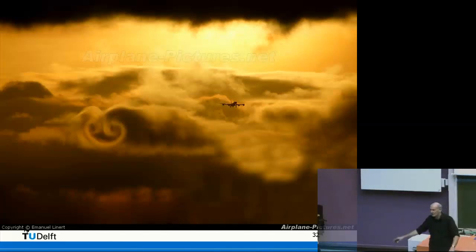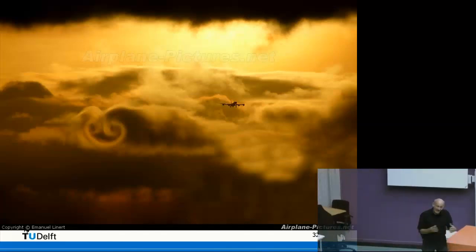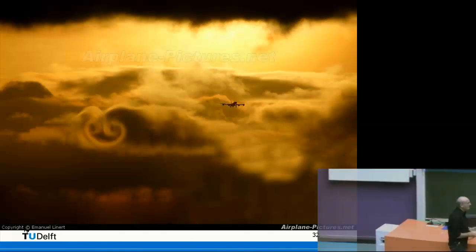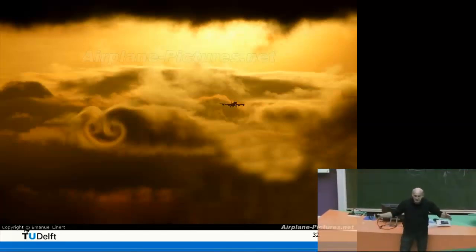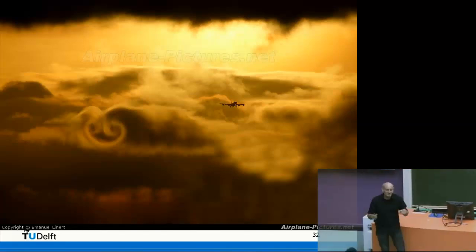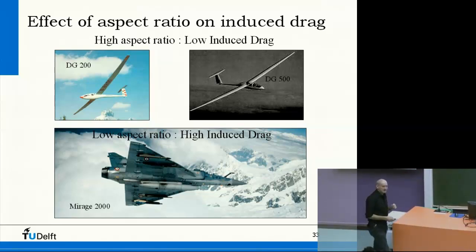They are there for a long time. And if you have a very light aircraft following a very heavy aircraft, and then you just flip, right? So there should be some distance to have these vortices diffusing a little bit, because they are so very strong and persistent.